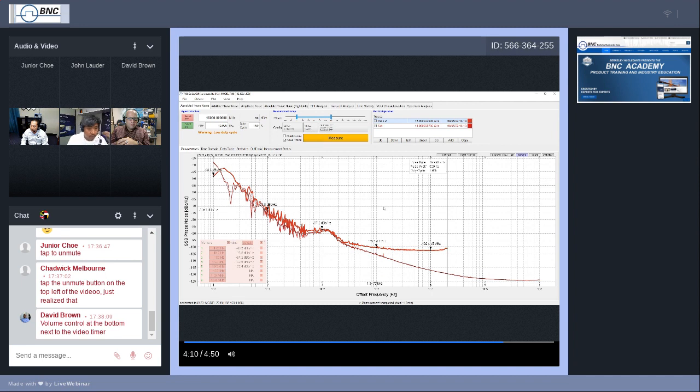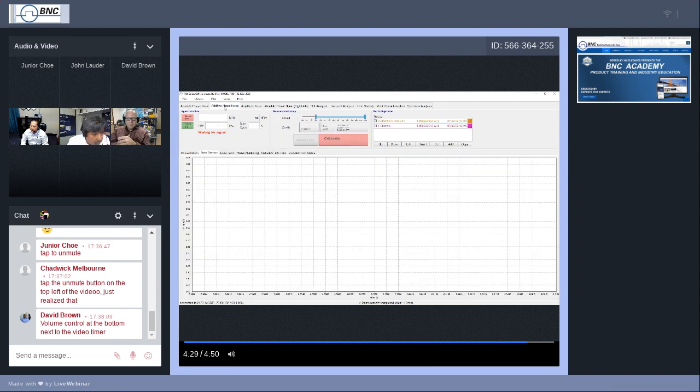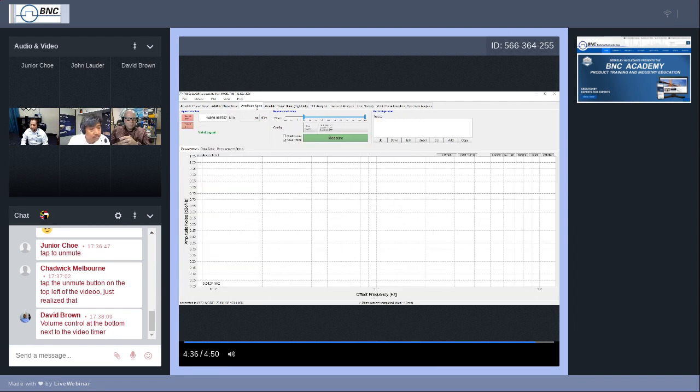Okay, it completed the measurement in about 1.6 minutes total, including the locking. And we have the plot or the trace on the absolute phase noise tab. Also, if you're trying to measure the phase plot of a pulse using an amplifier, it also supports the additive phase noise as well as the amplitude noise tab.